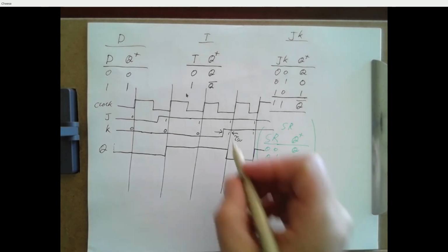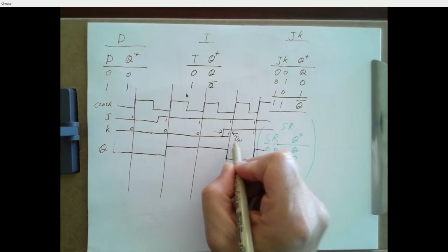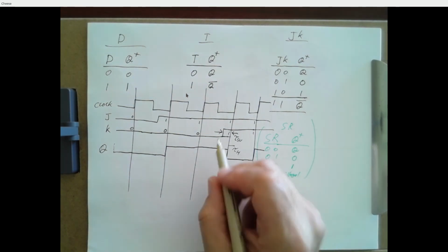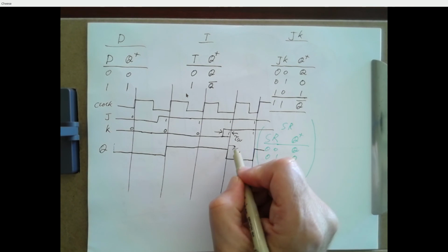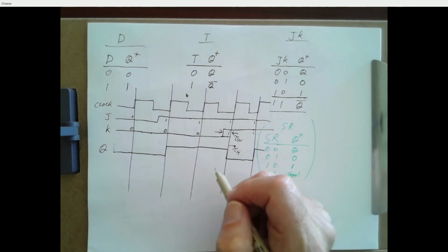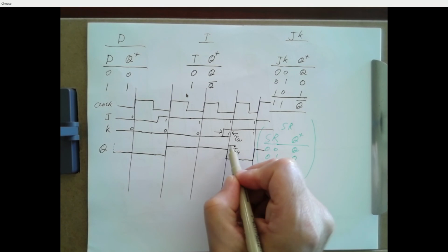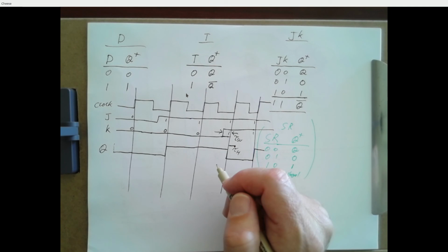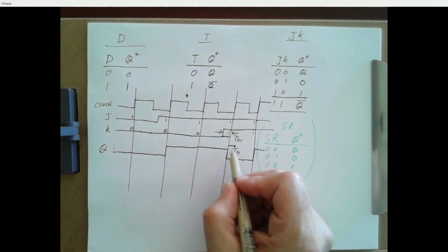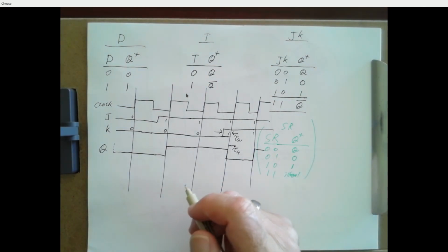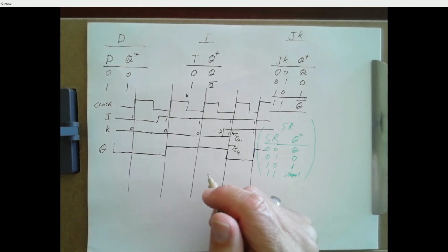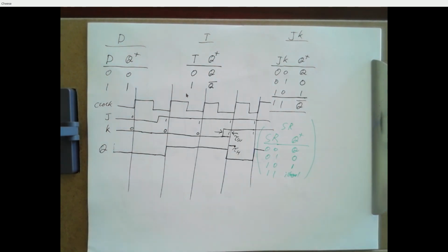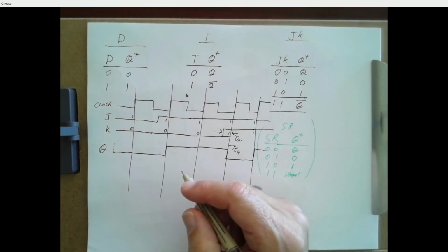We basically need to know what the minimum setup time is, what the minimum hold time is, and make sure we don't tick the clock anywhere between here and here. So if the time here and the time here adds up to 10 nanoseconds, the fastest we can clock the system is where a clock tick doesn't occur any sooner than every 10 nanoseconds. And we're down to 100 megahertz clock already. If it's 100 nanoseconds setup and hold time plus all the propagation delay, we can't clock faster than 10 megahertz.